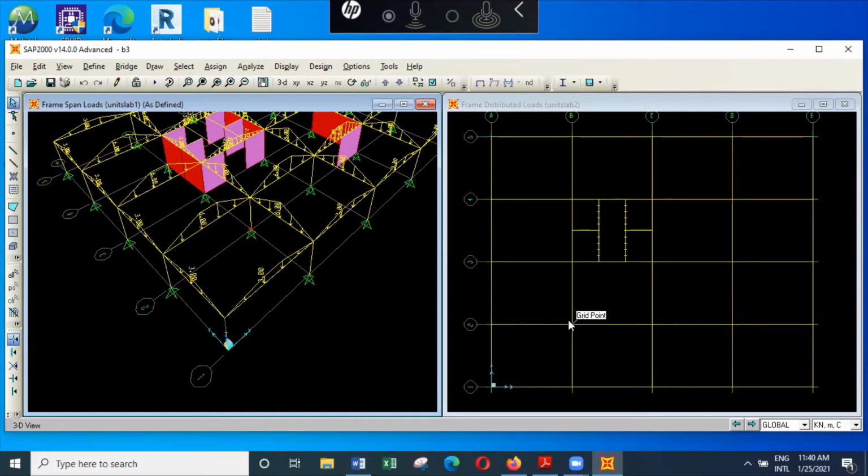So altogether 7.5. If you have a second beam here, then the span will be reduced to 3.75 meters. In which case, it may be possible to have even a slab thickness like 125 millimeters. So you can see, you can save about 50 millimeters of concrete.